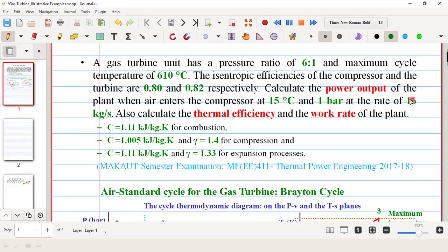If the mass flow rate is not given, then we will only be able to calculate quantities per unit mass. So you have to check whether, in a problem, the mass flow rate or such extensive properties like total heat transfer are given; if not, you will not be able to calculate extensive properties.